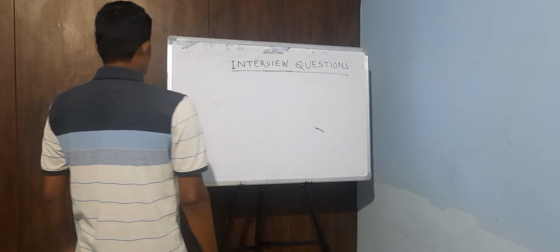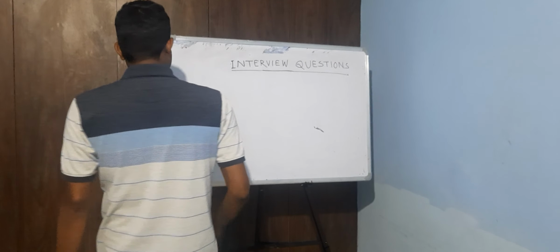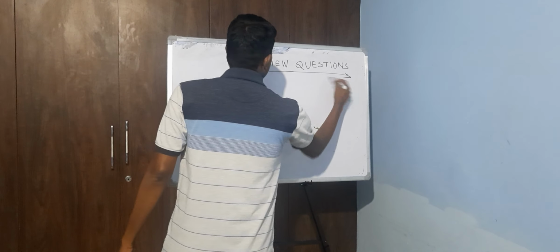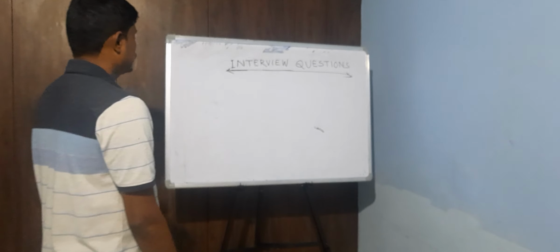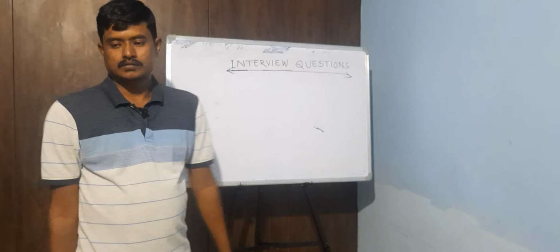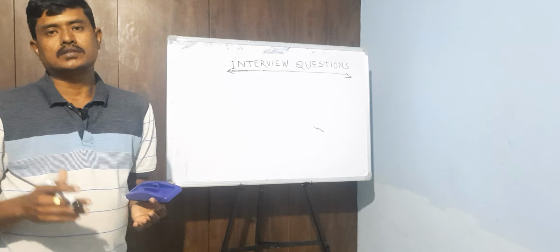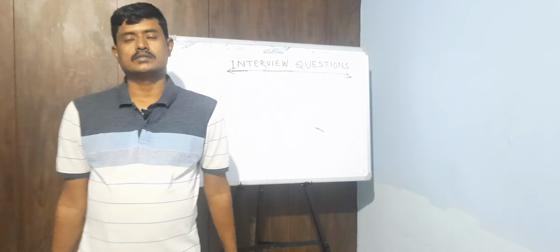Then come to the losses, that is copper loss and iron loss. The maximum efficiency occurs when the iron loss equals the copper loss.